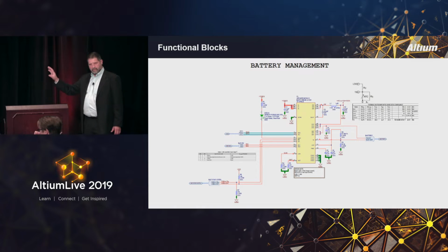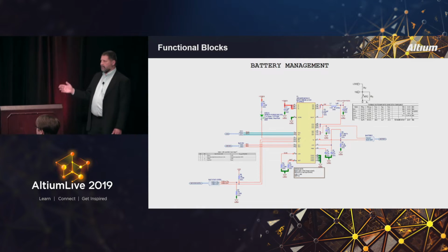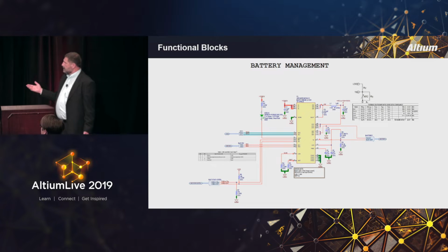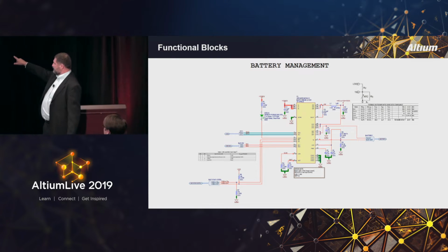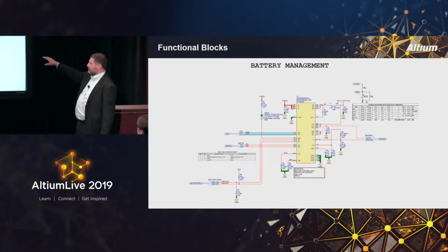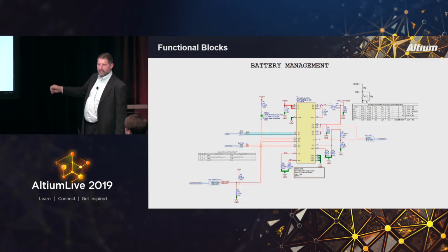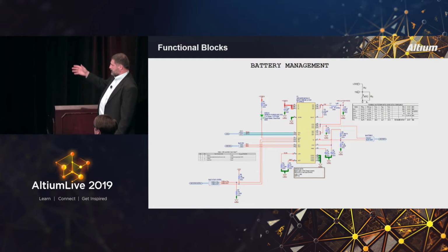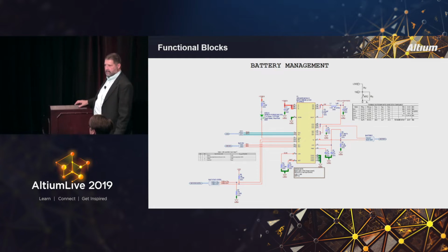As we examine each page as a designer, we're looking for things that are the highest priority to place. And if I'm working with the engineers, I review the schematics, and I would ask Max, is the placement of L1 critical? And he's going to let me know. Does that need to be close by, or is it okay a little bit farther away? Obviously, the diodes probably don't need to be close. But I'm going to be asking him those kinds of questions.